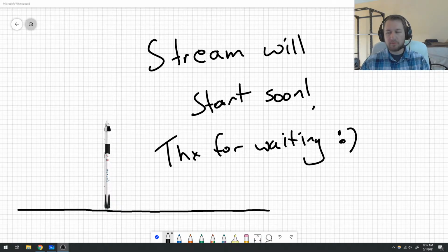You try to explore the software, and from the comfort of your code, you can try out different things, right? So that's sort of why I wanted to make a Kalman filter for this. You don't need one, at least for altitude, but it does help slightly, and the bulk of it is from the barometer.